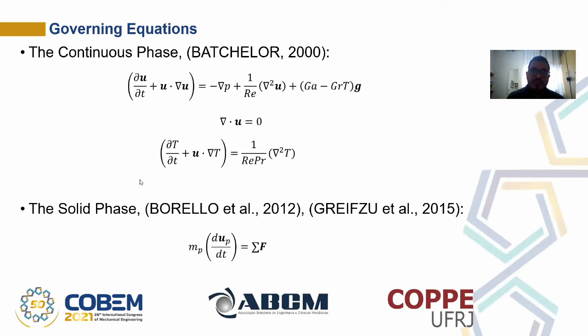For the advective problem, we have the Galileo number and the Grashof number for the temperature gradient. And for the expansion problem, we have the Reynolds number. So for the advection problem, the Reynolds number is set to 1. And for the expansion problem, we have the Grashof and Galileo set to 1 or 0.